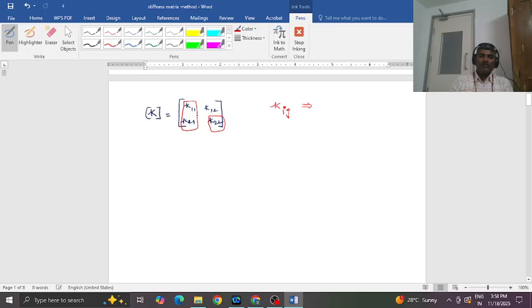So what is I and what is J in this one? So J refers to the displacement coordinate. Okay, I refers to force coordinate. It's just inverse of what you have learned, Fij, flexibility. So now what does this mean? You give unit displacement and calculate force required to get unit displacement. That will be your stiffness value. Because stiffness from basic formula is P by delta. If you make delta 1, that is displacement is 1, then your P becomes K. P is equal to K. Which means give 1 unit displacement and calculate force required to create this 1 unit displacement.